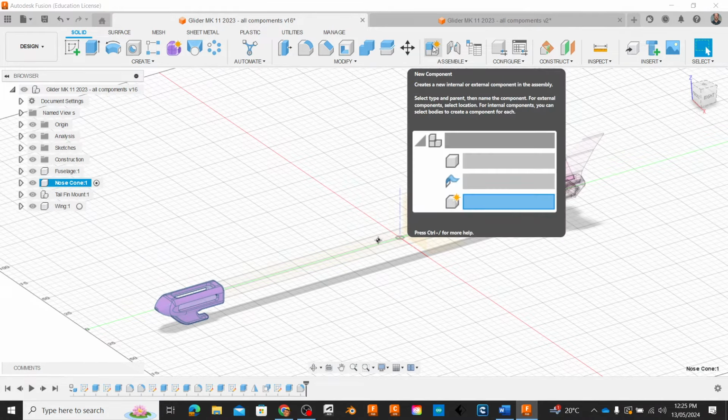So what I'm going to do here is space out a series of planes. I'm going to go from 0 to 150 millimeters out. Our wings are 300 millimeters wingtip to wingtip. So I'm going to start that process now because I'll recopy this sketch and then copy it to the next plane out.